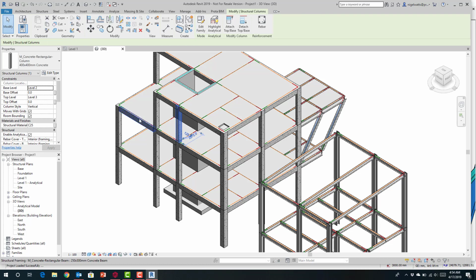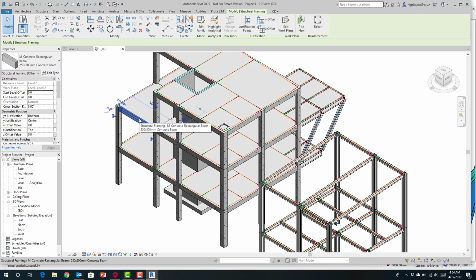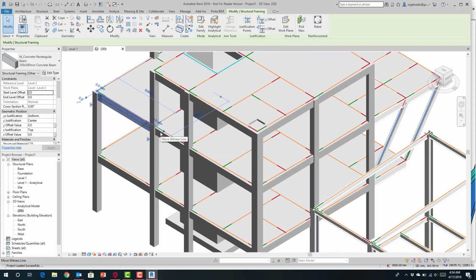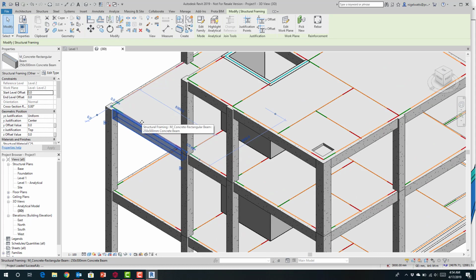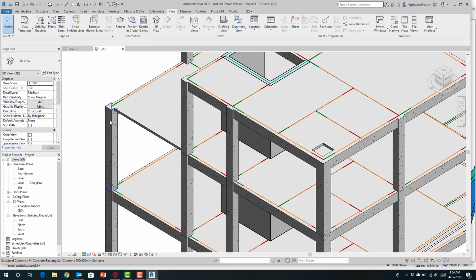Once you've got the model in Revit, you can begin the process of coordination. Obviously within a typical Revit model, you'll also have the architecture, so you may have doors, windows, other architectural cladding finishes and the like in the model, and this initiates the process of coordination. If the mechanical electrical services are in the model and a beam was perhaps clashing, then you can pick those up. At this point you may run Navisworks, integrate the architectural model in and begin the process of coordination. At any time during this process, you can make changes to the model in here.